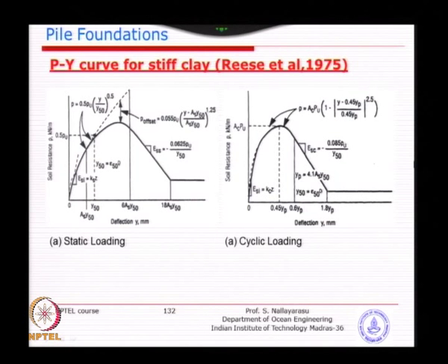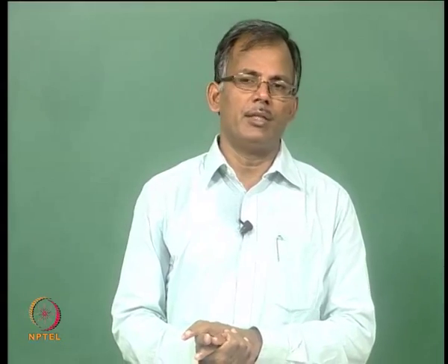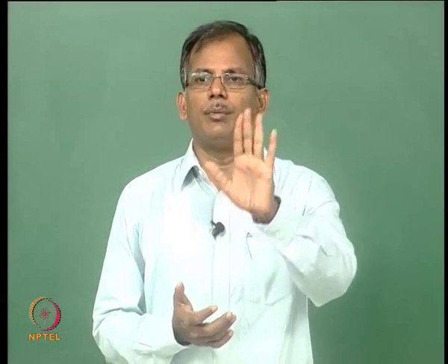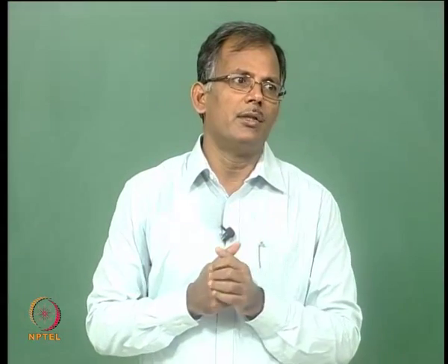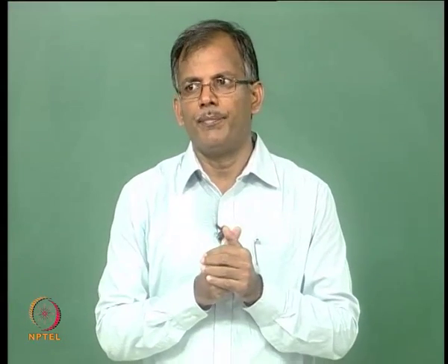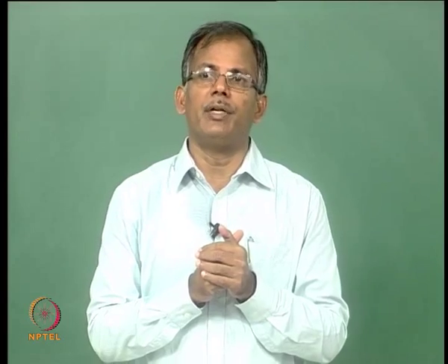The next one we want to look at is the stiff clay, as the demarcation between the soft clay and the stiff clay. We need to understand why we need to differentiate. We always think that higher strength means better, but it is not always like this, especially with respect to cyclic loading, when the pile pushes the soil forward and the pile alone comes back, because there is no contact or adhesion effect if the clay is very hard.